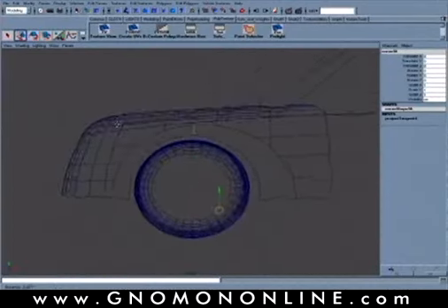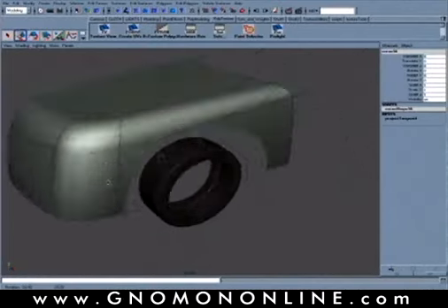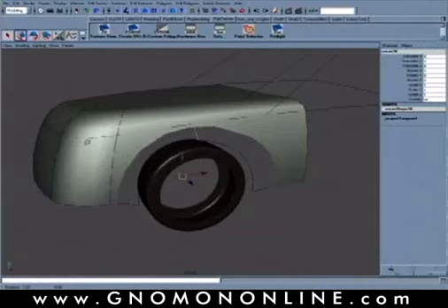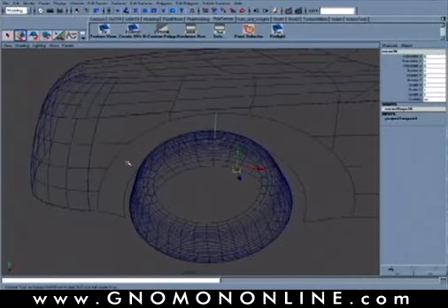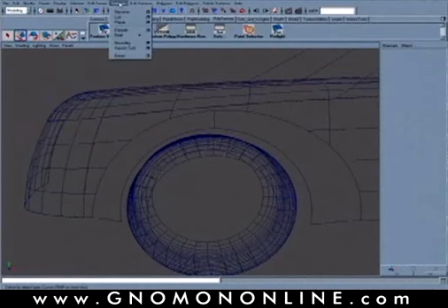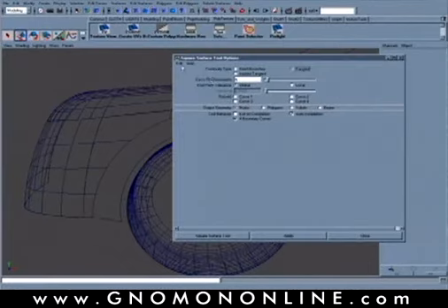Okay, now to actually build this surface, here's what we have so far. So we have our model of the quarter panel and wheel, and then I want to go in and integrate this piece here. And I'm going to do this basically by going into Square. Okay, so if we go into Surfaces and turn on the Square tool, I'm using this primarily as Square. I use it as a tool, not an action, meaning that I go into Edit and say use this as tool here. Okay, this just allows me a little more control, that I can go in and pick on all 4 curves and then it builds the square right away.